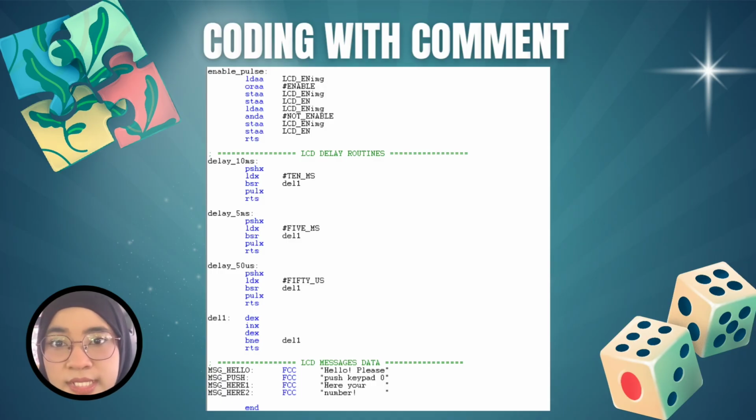After that, the delay routines like delay_10ms, delay_5ms, and delay_50 micros are used to wait for a short time. These delays are important because the LCD needs a little time to process each command or character. The del1 loop simply counts numbers to create the delay time.